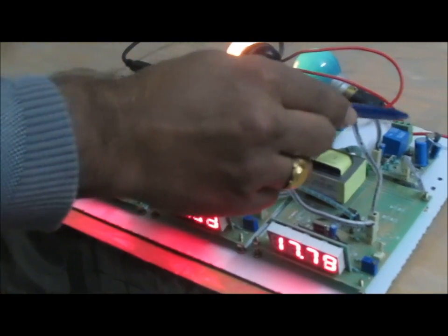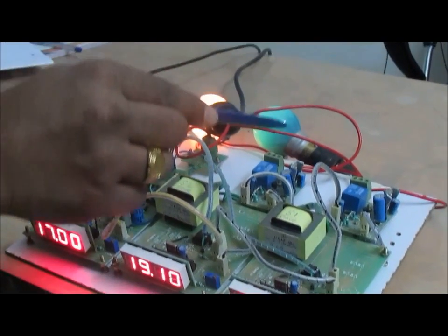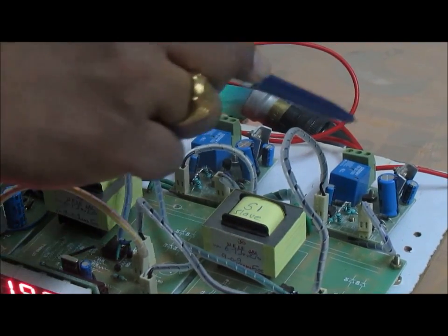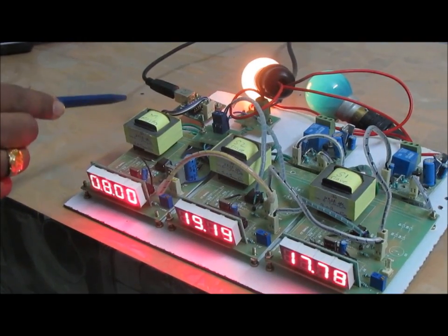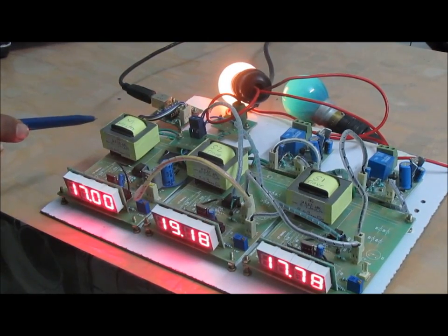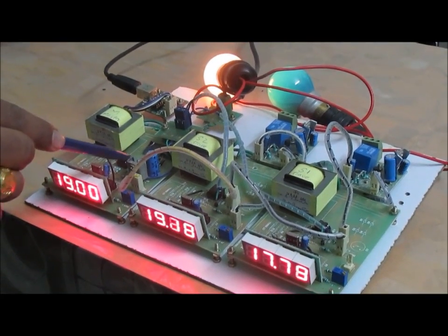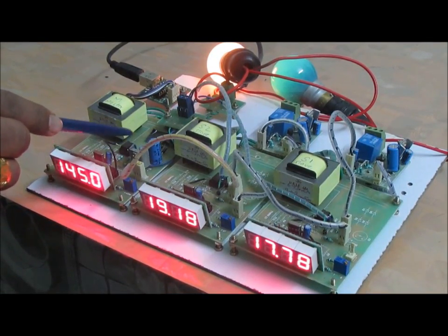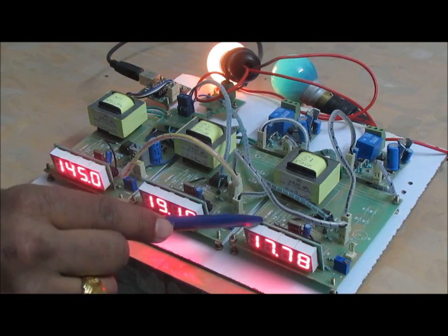Now this one is the relay unit, and this one is your bulb, which are connected to the NO and C terminal of this relay. These are transformers, which are converting 230 volt to 9 volt AC, and this one is your bridge rectifier circuit, and this one is a 7805 for regulated power supply. This 7805 is giving this supply, 0 to 5 volt DC, which is being used for this master unit, slave 1 and slave 2.